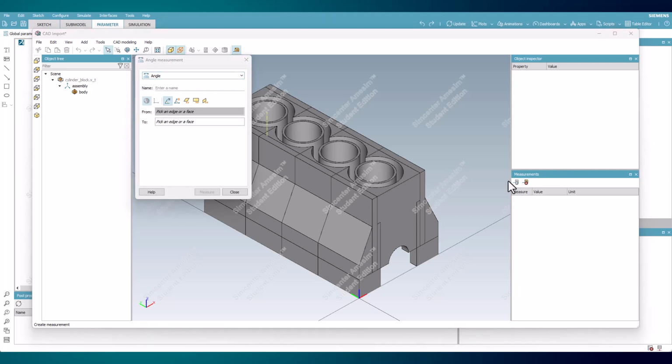A new window will appear that starts with a drop-down for various types of measurements the user can do. Following this is a name field to label the measurement, and last is the criteria needed from the CAD to determine its value. The measurements needed to start discretizing the model are the distances from the front face of the block to each of the pre-marked sections.